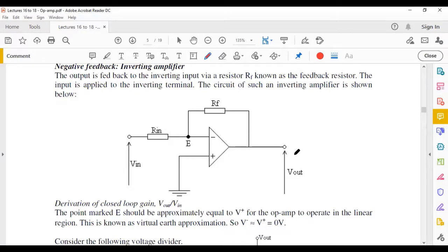The circuit we considered earlier in open loop mode, you can liken this to instability, meaning your output is only plus Vs or minus Vs. So it's always saturated. It's always completely filled, if you want. If you want an output signal which is not saturated, with better stability of your output, then you're going to have negative feedback. What is negative feedback? Basically, it's about feeding part of your output to your input. When you do that, the circuit becomes more stable, and it will not be saturated at plus Vs or minus Vs anymore.